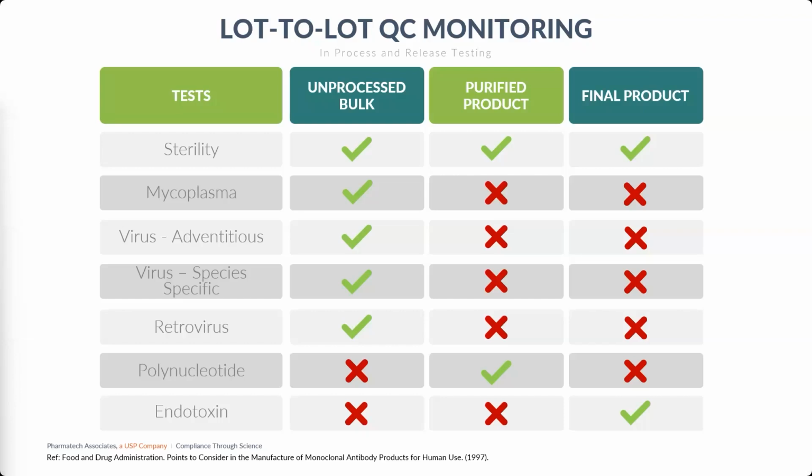And again, much like cell line qualification, we start thinking about the product that we're manufacturing. Of course, sterility, because we're touching that product in a number of manipulations throughout the process, whether it's coming out of the reactor, or going through chromatography, or going through viral removal, there's always the potential for a sterility issue, right? And that's a microbial and viral infection at any given point. So that is testing that is required at basically every step along the way, from the material that comes out of your bioreactor all the way through your final packaged product.